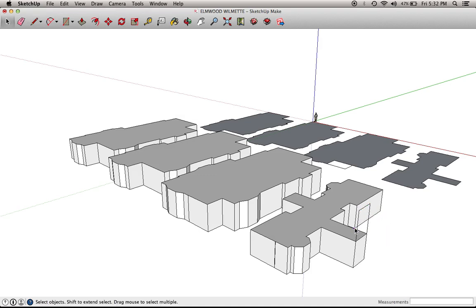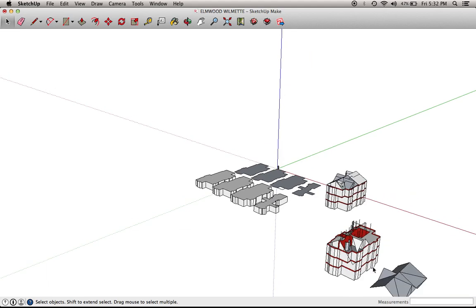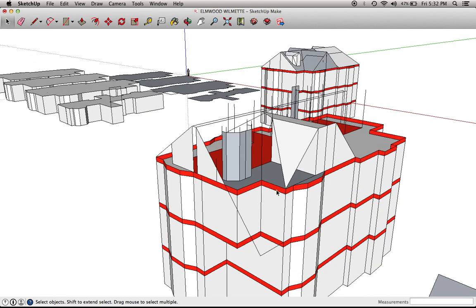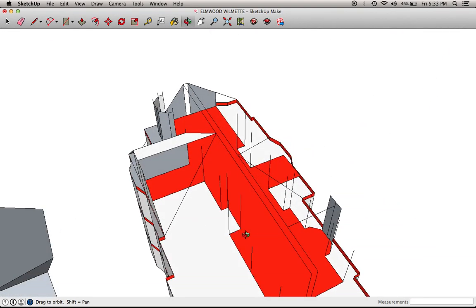Okay, so once we have these 3D sections of the floors, then I put them all together like so. And I have also drawn in the rim joists, and I do that by simply putting these things on top of each other with a gap of 1 foot between them, and then I connect the dots to make sure that there are actual objects here. I can select all of the wall areas, select all the rim joist areas, etc. Really, really helpful.